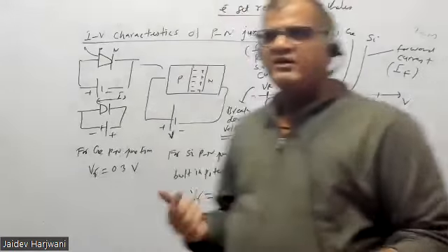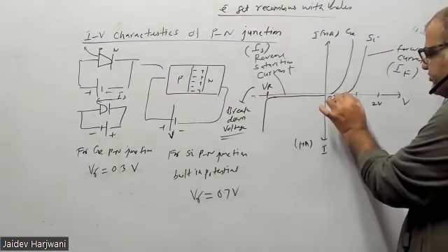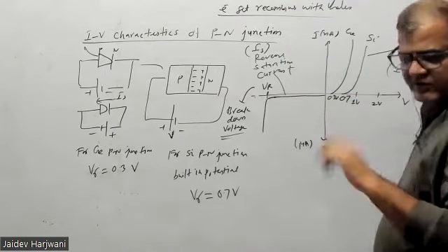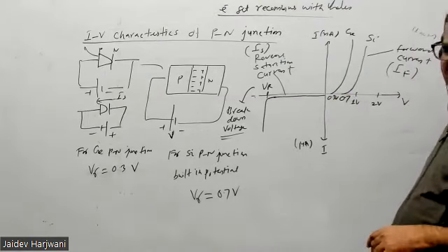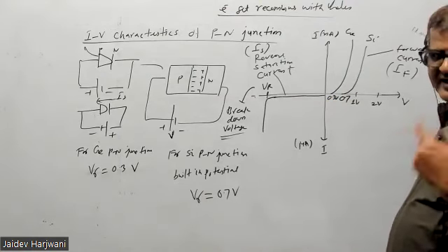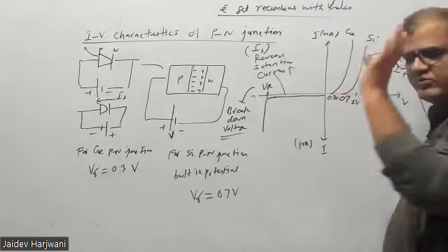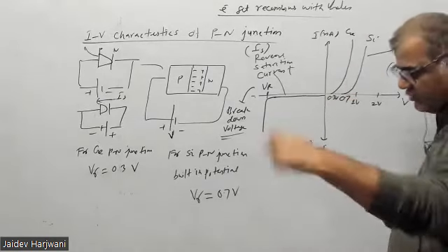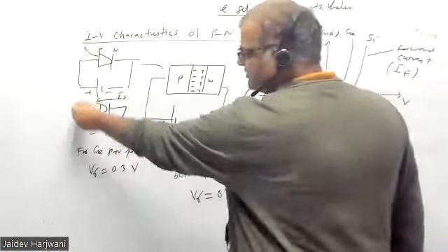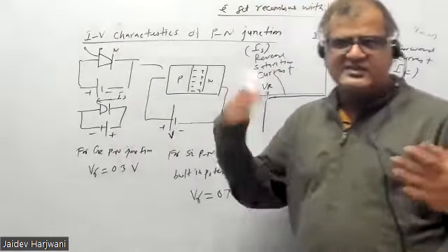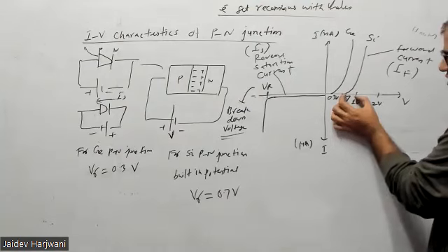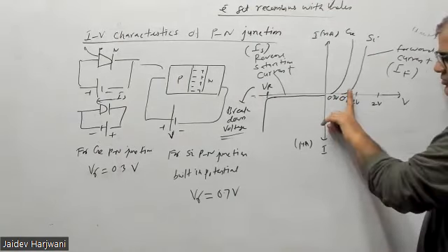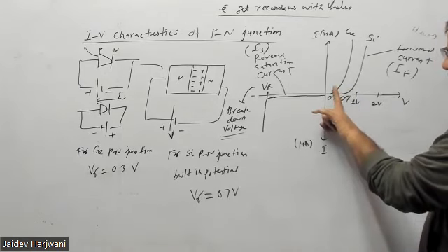Here we assume that because the voltage variation is very small, even though you keep increasing the voltage across the diode, the voltage will not increase; it will remain constant at 0.7 for silicon, 0.3 for germanium. Because the current increases exponentially, for practical purposes I can assume the voltage drop will be fixed for diodes.